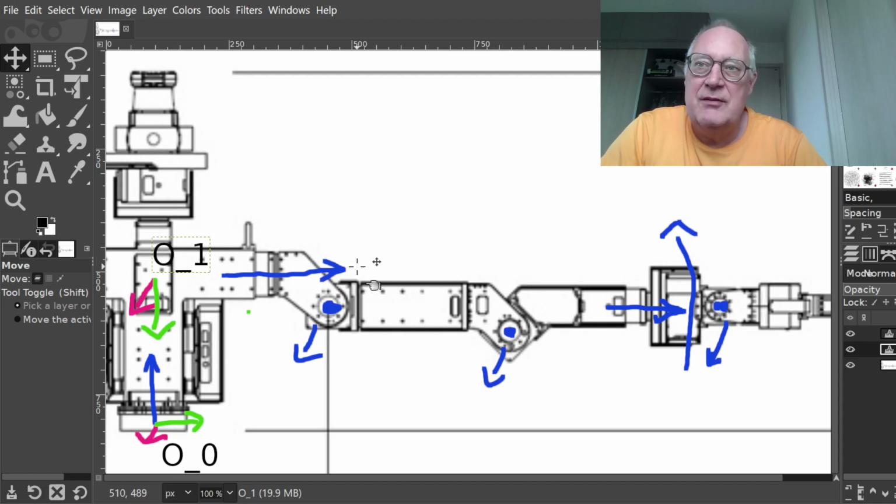Then they want to have the DH table if you want to implement kinematics or discuss kinematics with them. They want to have exactly those 4 numbers. With humanoid robots, since I don't need to communicate the kinematics in such a way, usually I have a little bit more freedom, and I like to have the coordinates